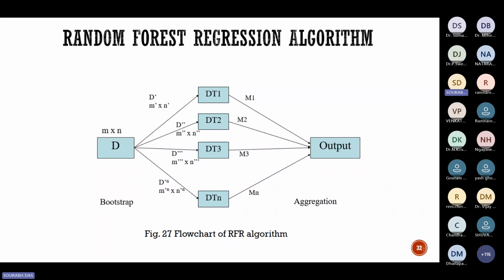This is the output of each individual decision tree. After getting the output of each decision tree, the final SOC estimation is derived by averaging the outputs from all the decision trees, which helps to improve the accuracy of the SOC estimation by minimizing the variation across the individual trees, and it gives a robust estimated SOC value.